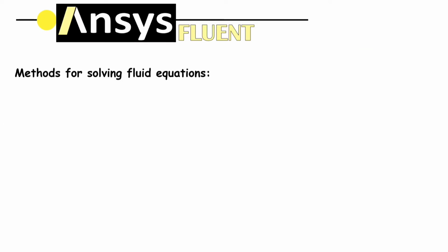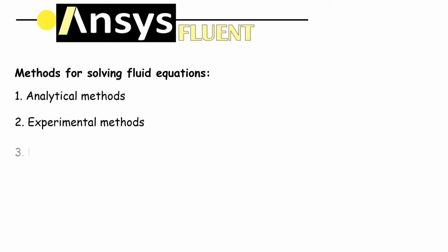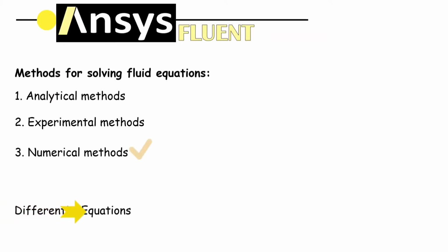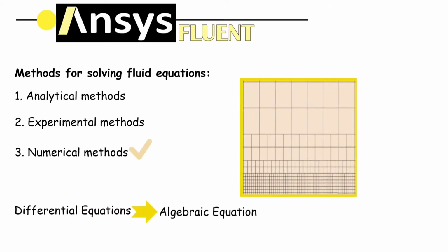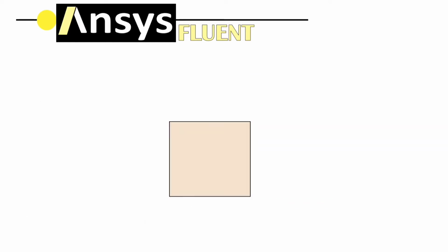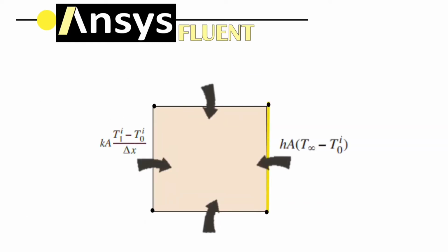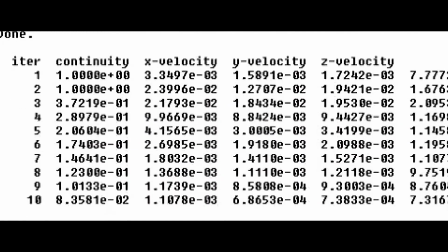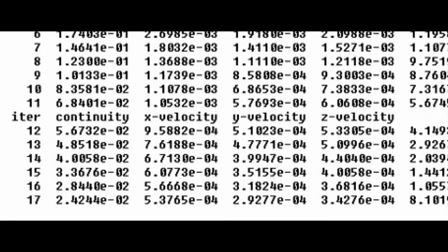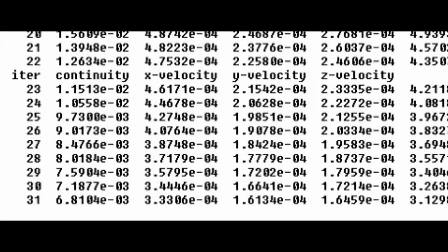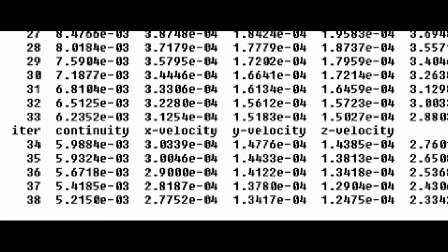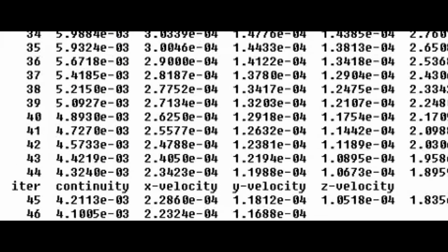In this study, among the methods for solving fluid equations, we deal with the numerical solution method of equations. In the numerical solution method, differential equations are converted to algebraic equations, and by dividing the solution domain into smaller cells, elements, and applying boundary conditions on them, a system of linear equations is created. By solving this system for all elements and with many iterations, which is the basis of numerical calculation methods, finally we come to an approximate answer with appropriate accuracy.